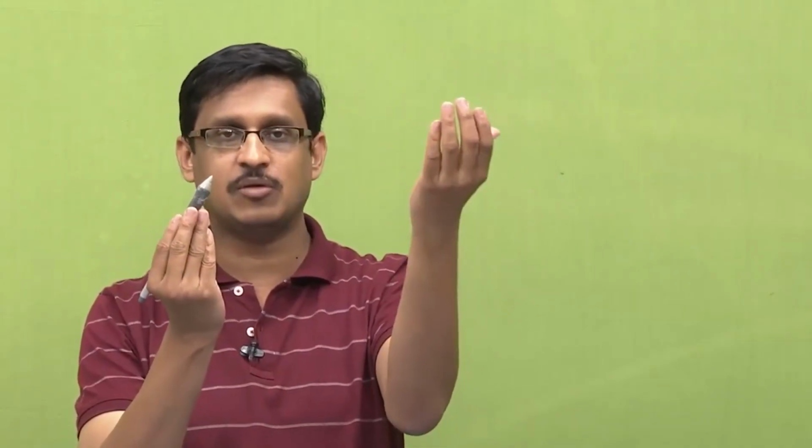So, if you want to describe the propagation of electric field and magnetic field, the radiating electric and magnetic field in the region between the two transmitters, I mean between the two antennas, there is no J and rho v there, right. But these J and rho v are required at the transmitter antenna side to actually generate E and H.